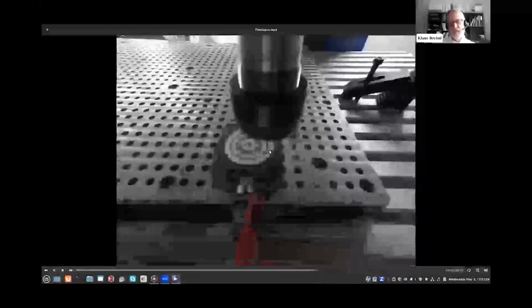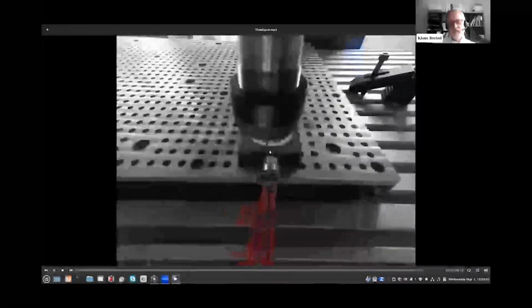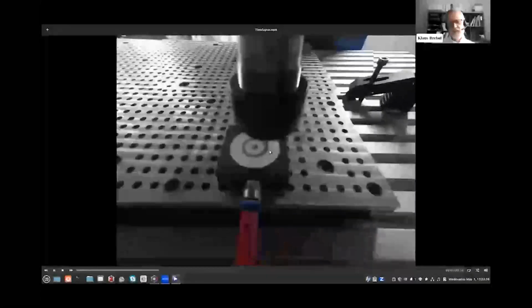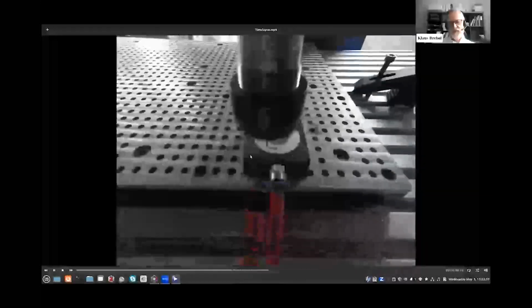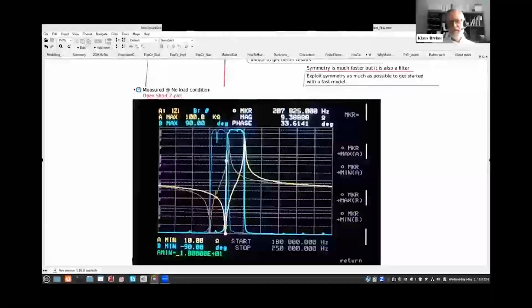It's actually a disc with a full electrode, and then we just grind a little bit through the electrode to make the electrode pattern that we want. Once it has been made on the top side, we flip over the device and get a similar pattern on the back side. However, a machine like this is not super precise. In the end, it turned out that our small bump is an asymmetry, because the trace was 200th of a millimeter deeper on the back side than it was on the front side.